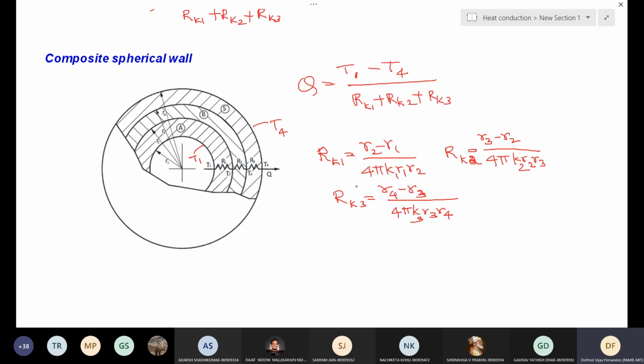The very low temperatures there, and the outside room temperature, so there is heat loss to the surroundings. There will be multi-layered insulations. In addition, radiation heat loss must be minimized, so radiation shields will also be used between the layers. That multi-layered composite wall is much more complex, but the problems we consider in this course are much simpler.